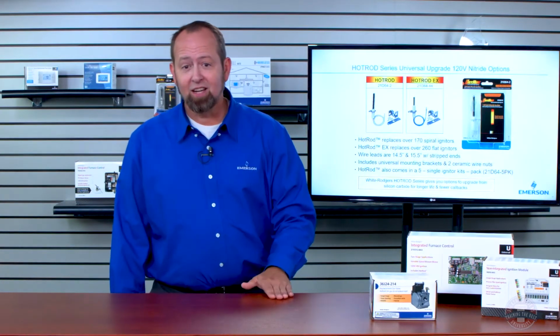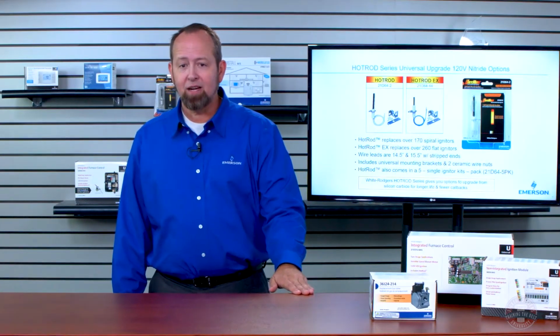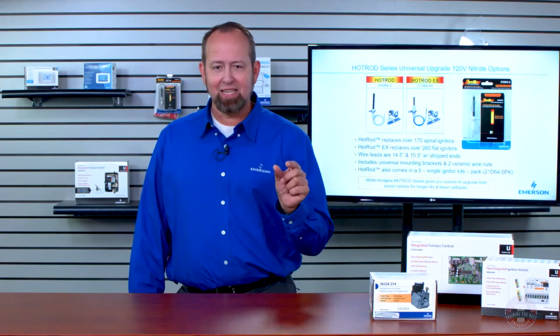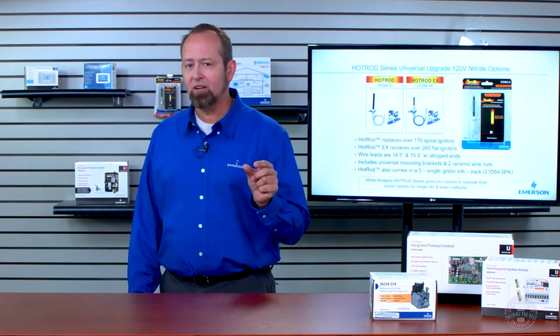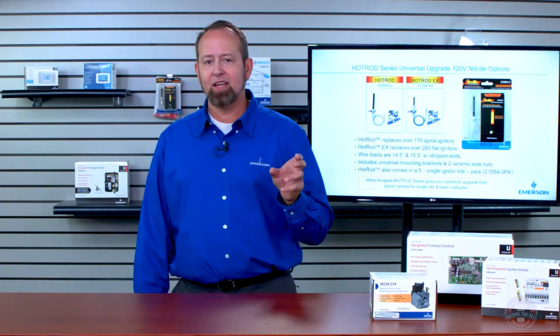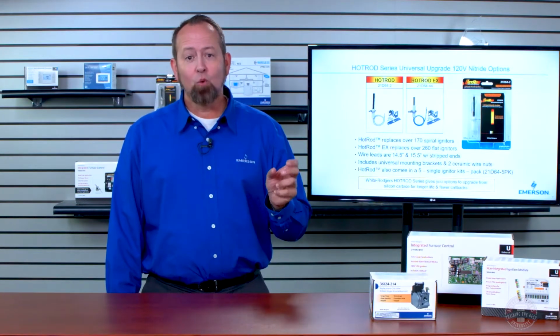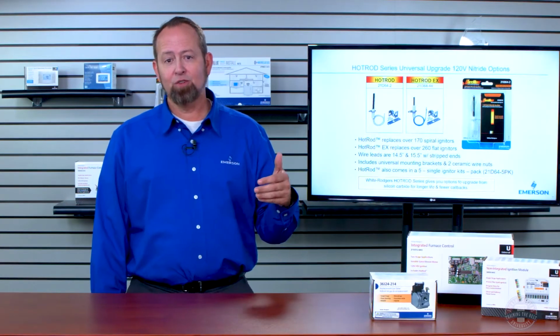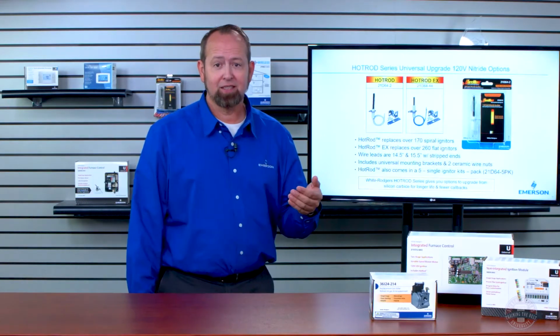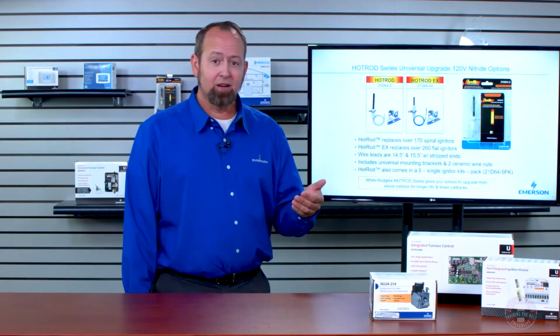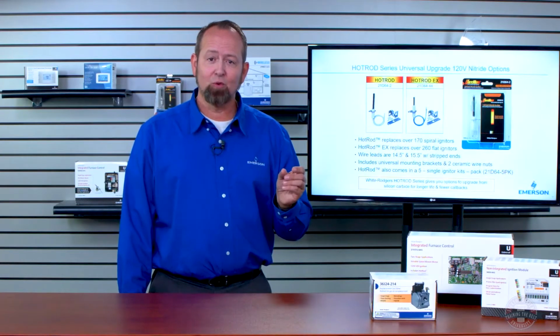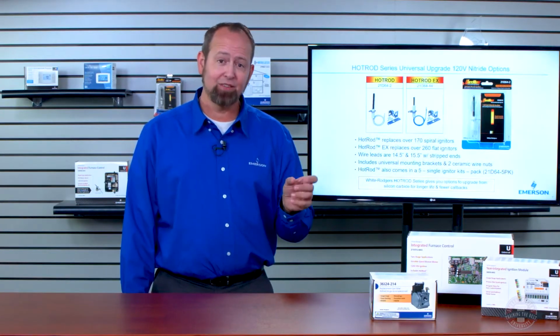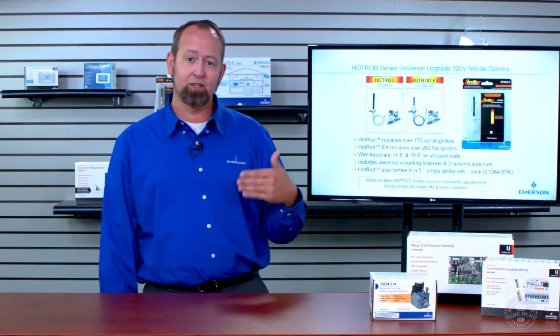That's a good question, Todd. The warm-up timing does matter, and there are some igniters out there that were called micro or mini igniters. They were small igniters that had somewhere around a 7-second warm-up time. They were known to go out very fast or to fail fairly fast, and that 7-second window was all that was given to them because of the type of material in their design.